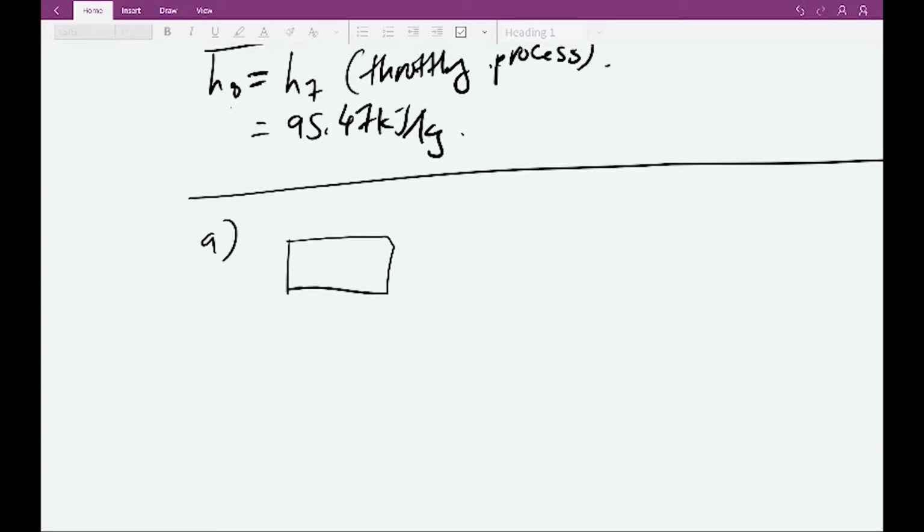I sketch again my refrigeration cycle, lower and also upper. Why is the mass flow rate different? Because it consists of different parts, different pipes, and it is not mixing together. So that's why it has different mass flow rates, and also we can use different refrigerants.